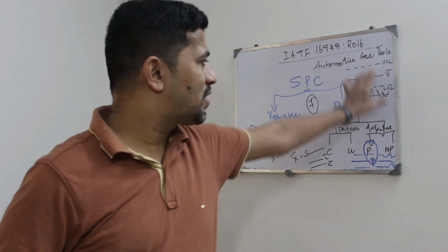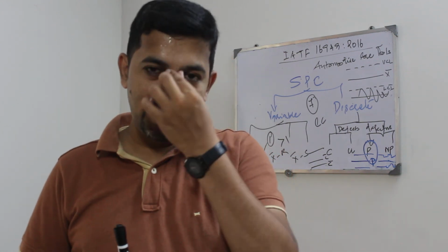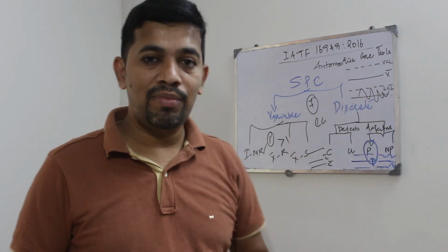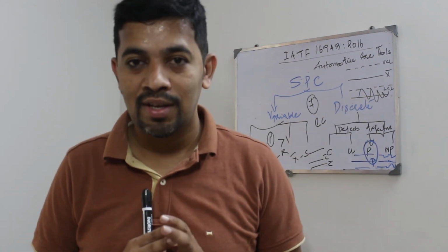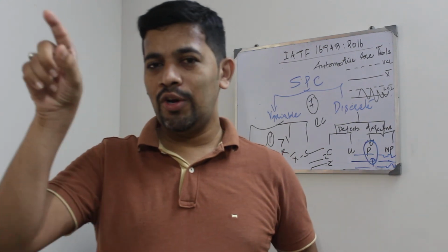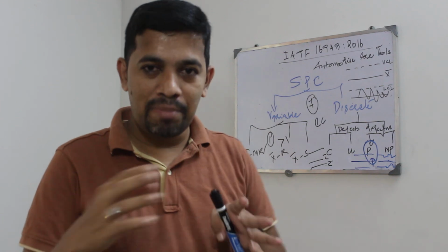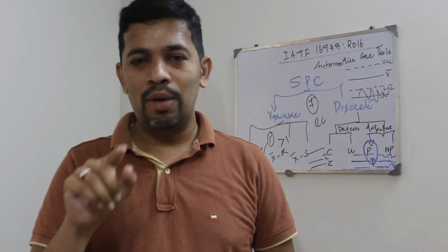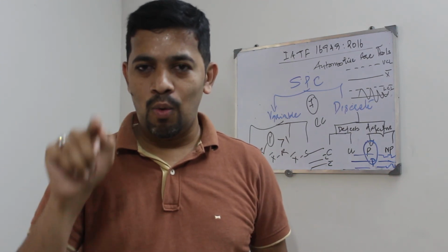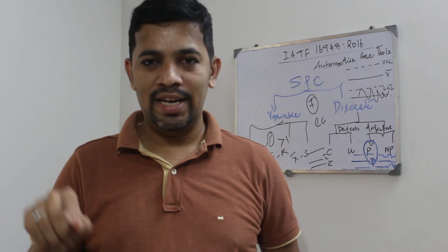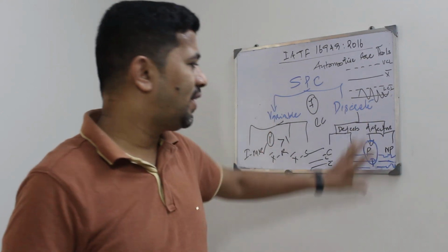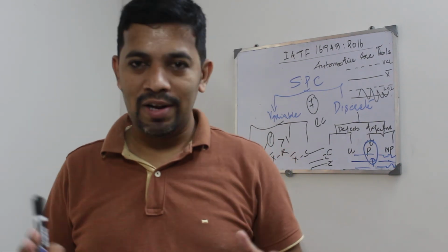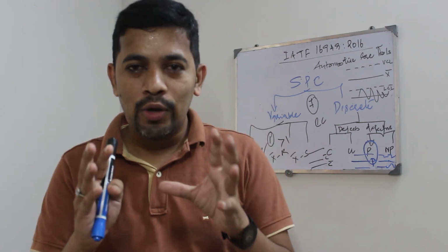Let's talk about all these. There is something called limit. For everything there is a formula for how to calculate the limit. This is not coming from the specification, this is coming from the process. For example, P bar, and you want to calculate the UCL of P bar, right? You already know the formula: P bar plus 3 root of P times 1 minus P divided by N. Like this, for all these things there is an associated formula. I have already done this in Excel, in many tabs. You can catch up to learn how to calculate the limit.